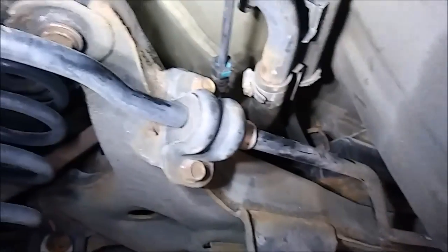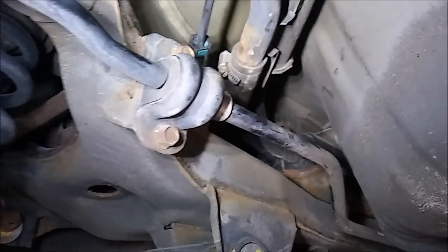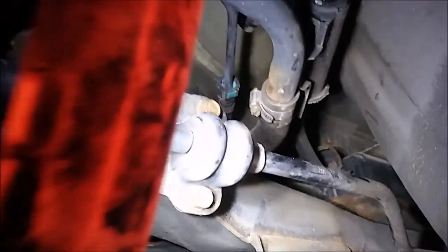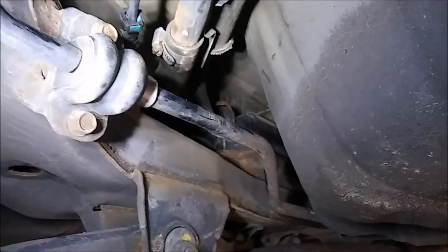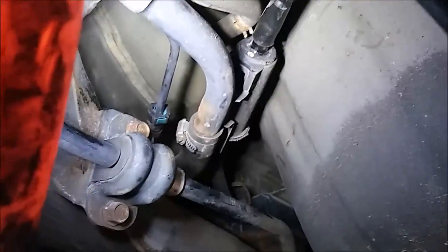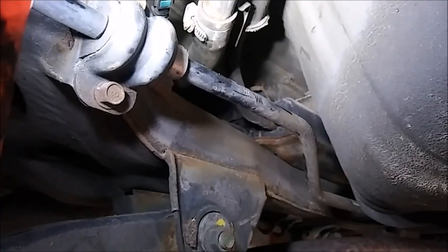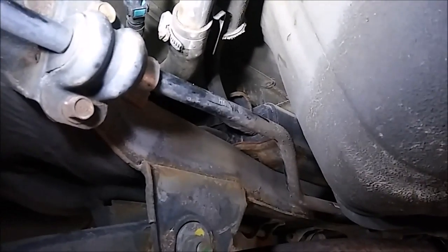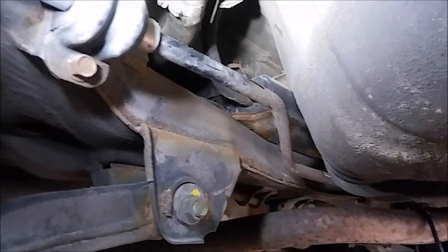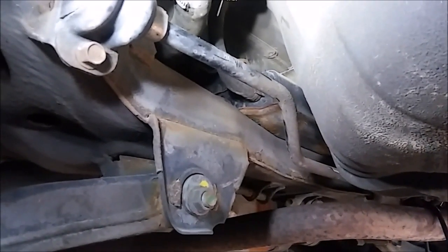I'm sure there's some check valves involved with some of these EVAP circuits, and that's why we weren't getting the results we wanted from this hose here, as well as from the purge solenoid up front. But anyways, I was able to identify this issue from this location here, testing there. So we got a little lucky on that one. As I said, I don't deal with EVAP problems on these very often, so it definitely came with a few challenges, not having bi-directional controls or anything like that.